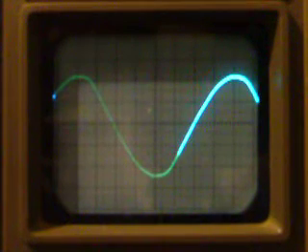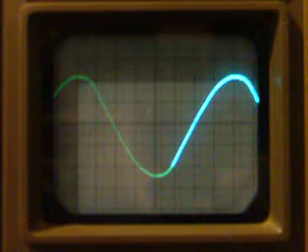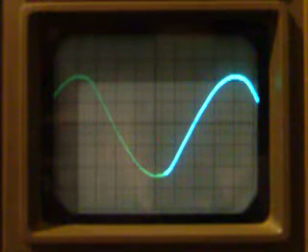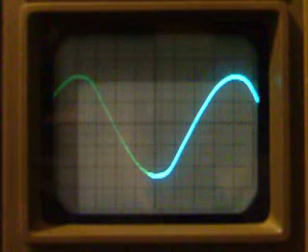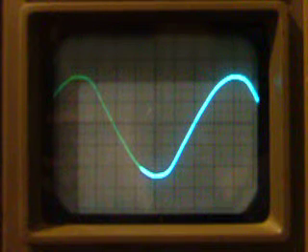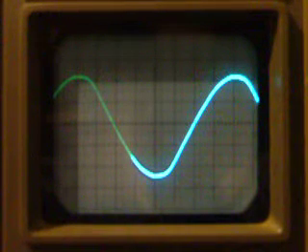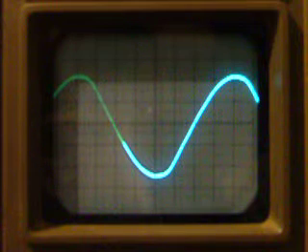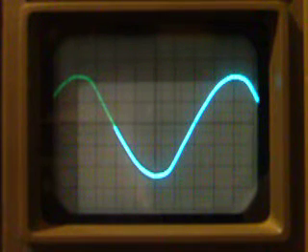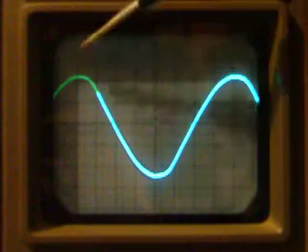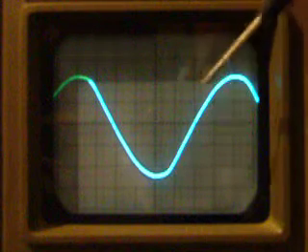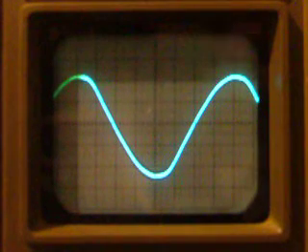So, what we have here is an HO amplifier in standby, and that is the heater winding output taken from one of the 100 ohm resistors, the virtual ground, virtual center tap. In standby we can see a little flattening here, but basically it's a sine wave.